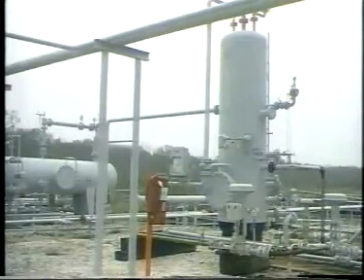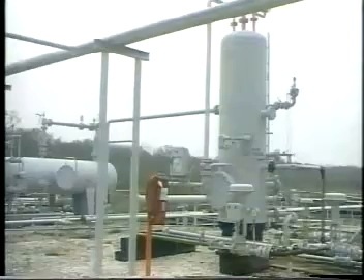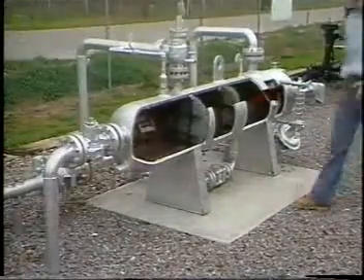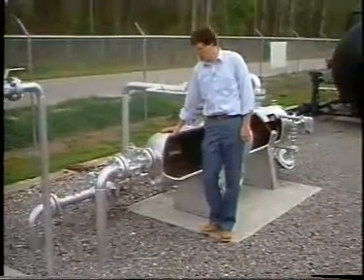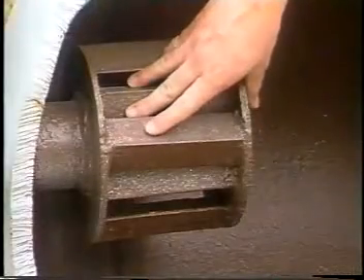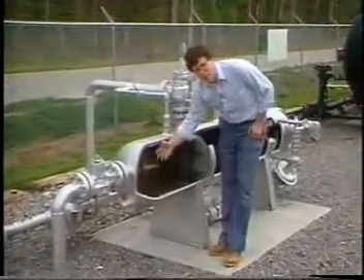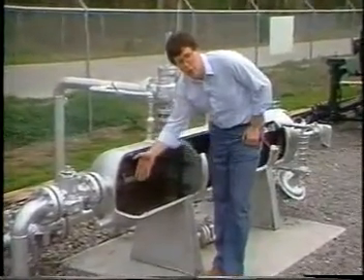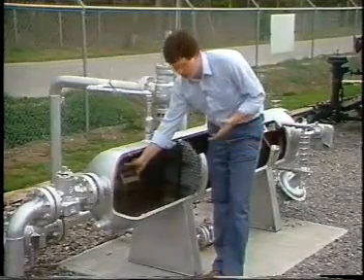Three-phase separators are designed as either horizontal or vertical pressure vessels. The only differences are that more space must be provided for oil-water settling, and that some means of removing the free water must be added. Here we see a cutaway version of a horizontal three-phase separator. The fluid initially enters the separator through this inlet and immediately strikes an inlet diverter. This particular inlet diverter is made of some pieces of angle iron which abruptly change the direction of flow of the fluid that's entering the separator. This does the initial gross separation of liquid from gas.